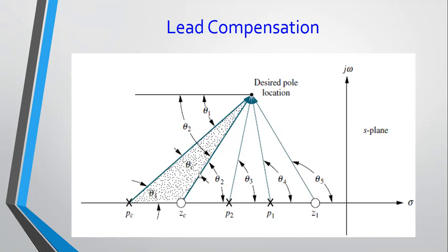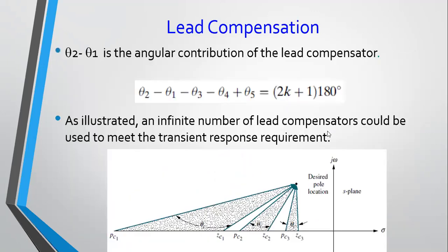That's what your lead compensator is giving. Before it was just θ2 with a 0 only. Now it's θc, which is θ2 minus θ1. This is the component being provided by your lead compensator now. Before it would be just θ2, like you see for the PD controller.